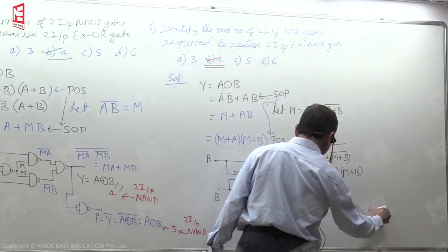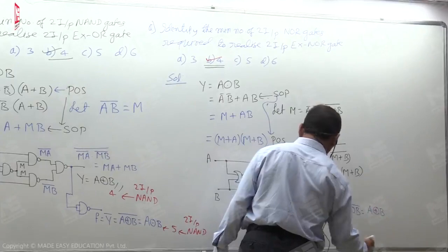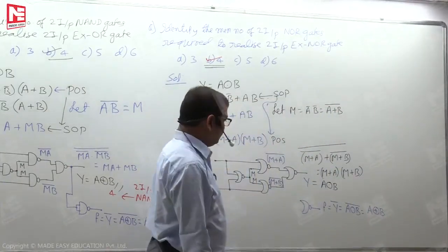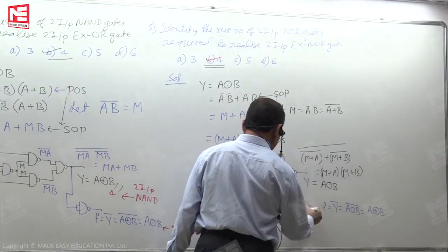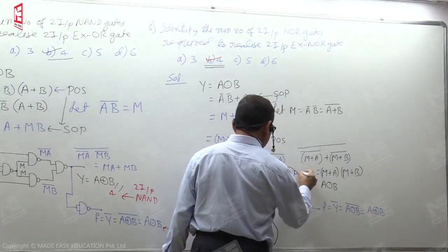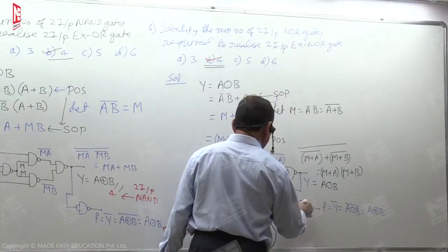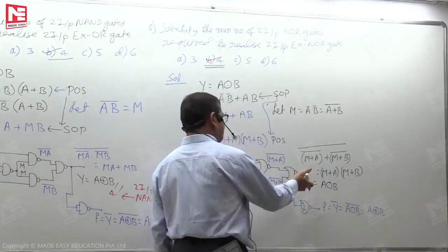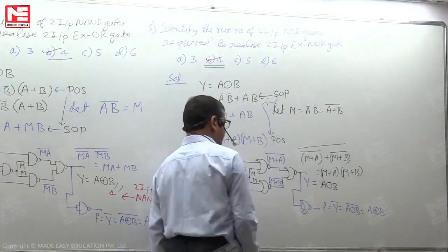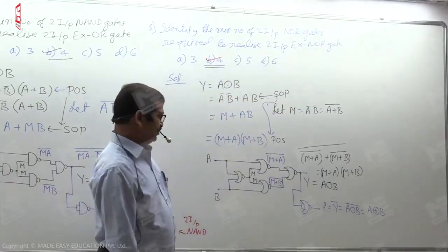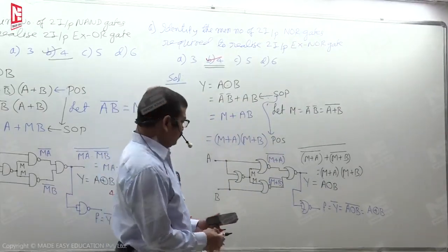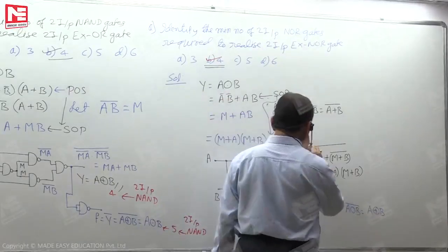So effectively, we get the exclusive OR between A and B. For this purpose, the 5th NOR gate we are using is an inverter, and the input will be Y.